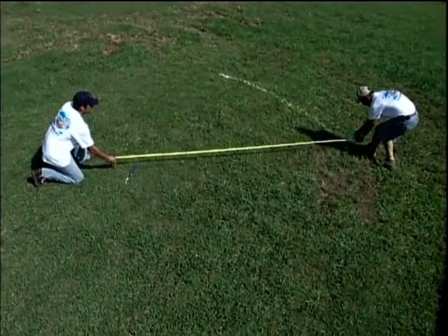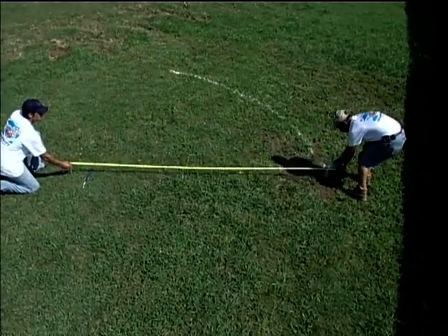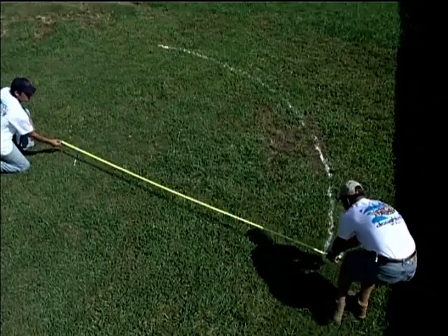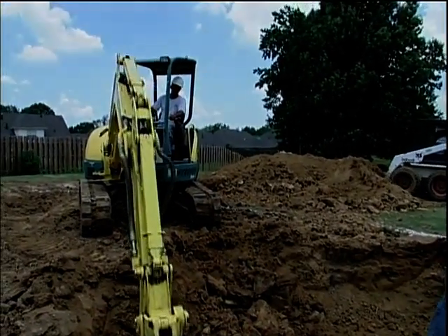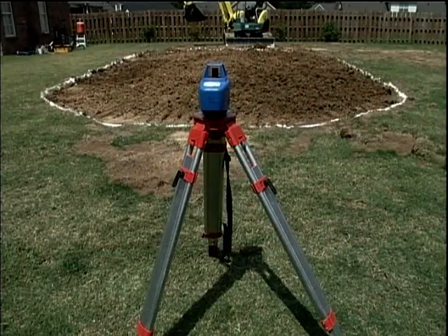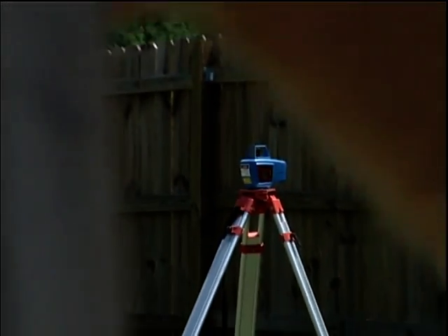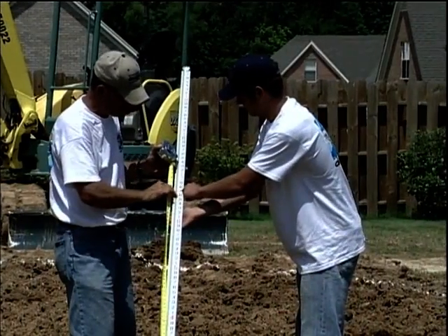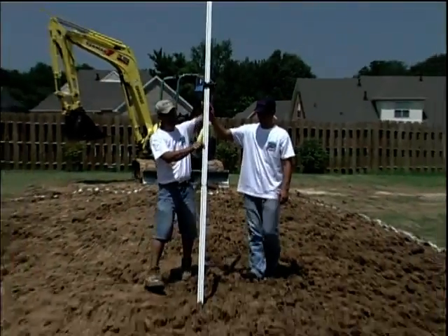Before beginning excavation, remember that each step must be followed carefully, because a below-grade pool installation is not as forgiving as an above-ground installation. For excavation, you will need the following tools: excavator, 2 square shovels, 2 garden rakes, a transit, and a ball of string. It is important at this point to establish your finished height. Set your transit and establish your finished height. Then you can add the pool depth to your finished height, and you will know how deep to dig.